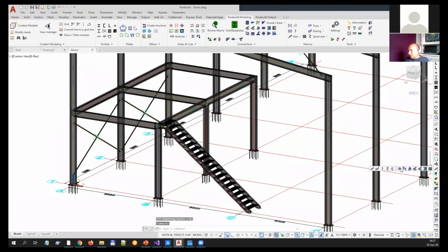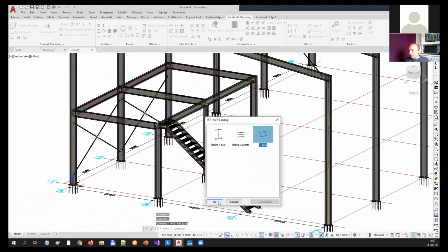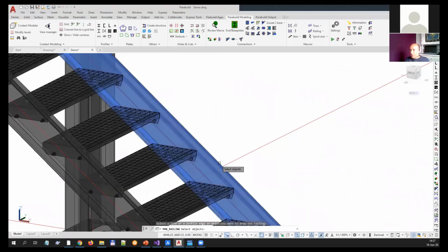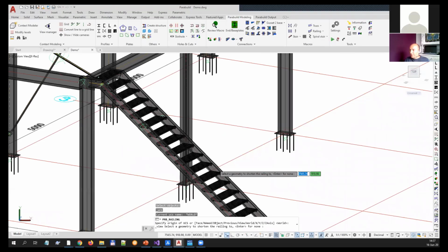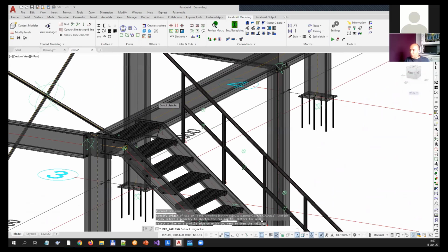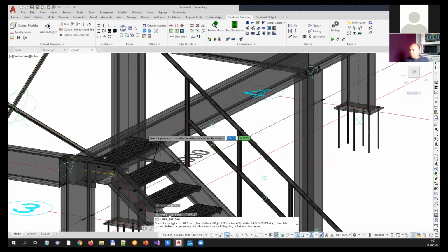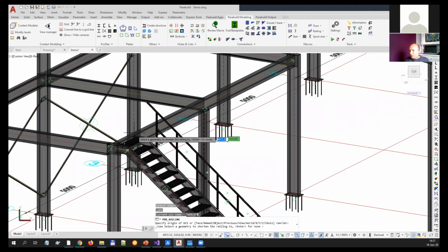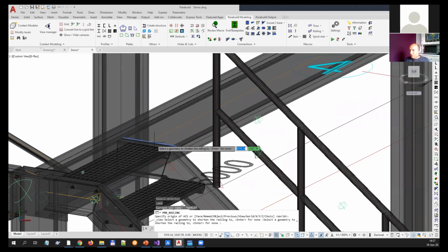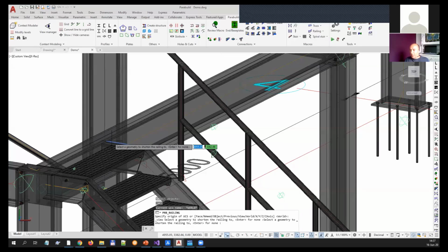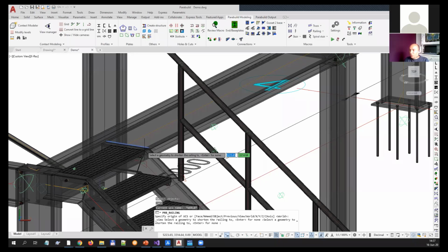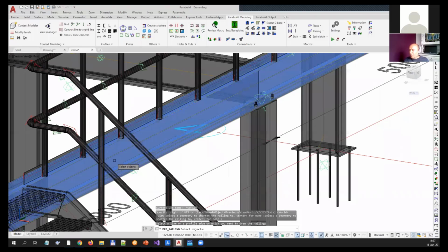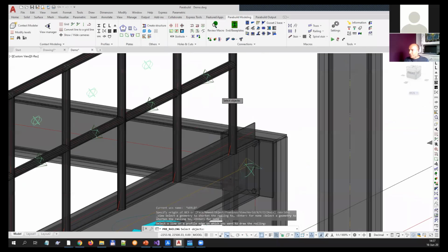And then I'd like to start drawing some railings. So it's better to select an edge on a profile. It's always the best method, if that's in any way possible. And I'm not going to draw it from here to there, but I'm going to draw it to there. So that's why I need to select an intersection geometry, and this is where the railing will stop. So you can see that those intersection tools that you saw for the bolts, it's the same thing that we can do here for the railing. So that's the second segment, and then another segment here at the end.